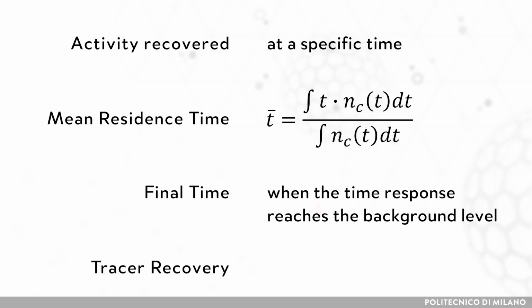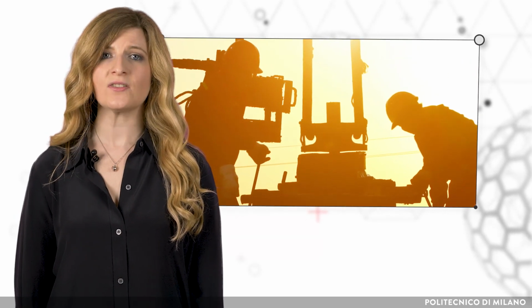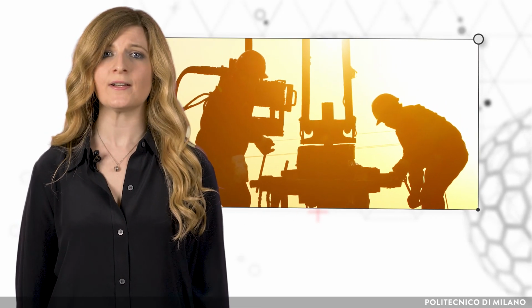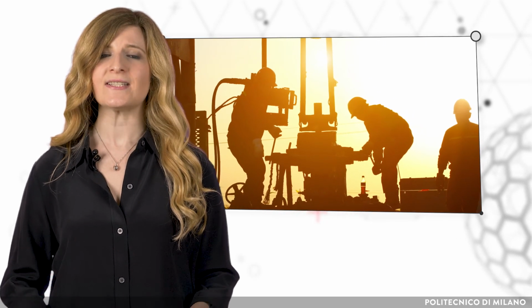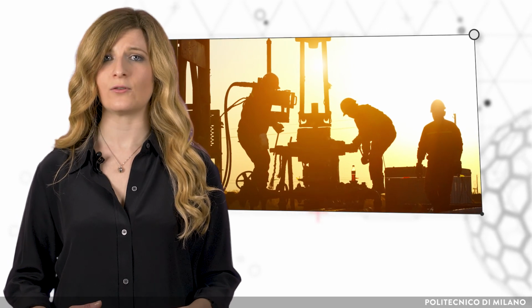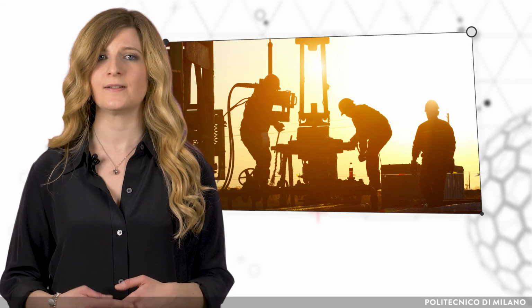In an ideal experiment, the tracer recovered is equal to the quantity injected. However, this is seldom higher than 80%, due to the fact that different molecules are blocked within the system, or go under the detection limit due to dilution, and so on. The interpretation of the response curves obtained gives correct and comprehensive information about the system hydrodynamic parameters. These allow better understanding of the phenomena involved and thus assist troubleshooting or tailoring the system performance.